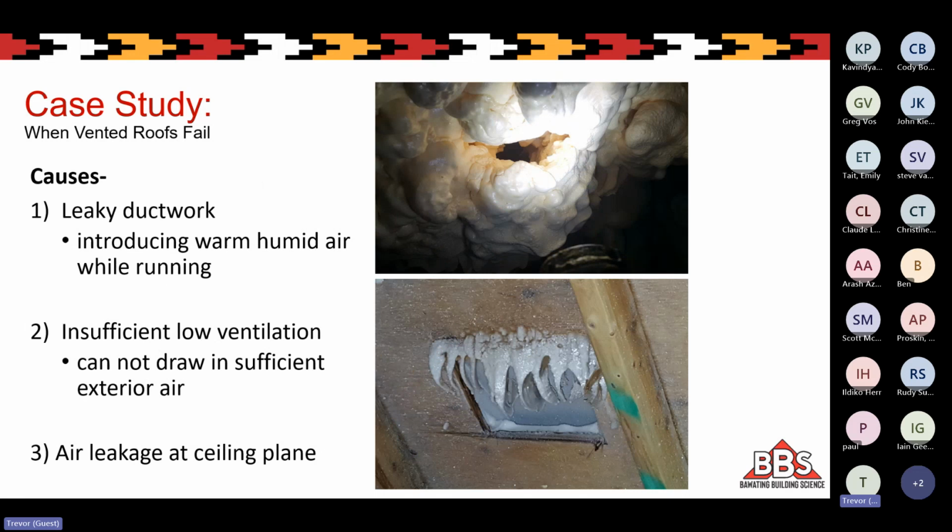Probably the bigger issue, though, is this ductwork. There's ductwork in the attic that is covered by this open cell spray foam. It was not installed in an airtight manner. As you can see, there's one example of gaps and holes in the spray foam. Basically every time the heat kicked on, at least some of that air was leaking out into the attic. And that's why we're getting positive pressurization in the attic and ventilation even outward at the low vent positions where there should be intakes.